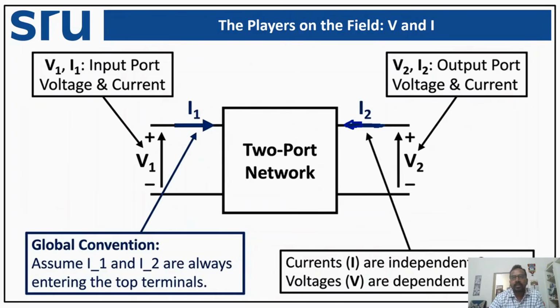Here C1 and C2 are generally present assuming that we have a circuit that has dependent sources. If the dependent sources are not present, that is, if you assume the two-port network is a linear circuit in the absence of dependent sources, then C1 and C2 become 0. So this interdependence of these parameters is what makes the two-port analysis both interesting and useful.